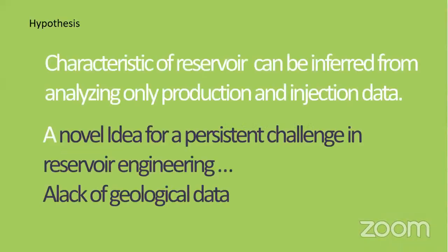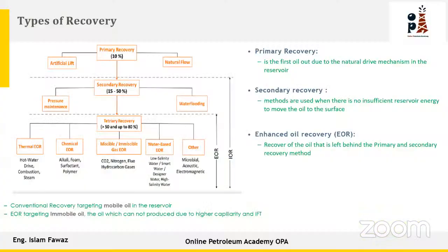So let's start with the introduction. I would like to emphasize this point, this is a hypothesis: the characteristics of any reservoir can be inferred from analyzing production and injection data. Also, most water flooding projects fall below expectations due to lack of geological data or lack of understanding of the geological aspects of water flooding. So this point is very, very important when you are working with a water flooding project.